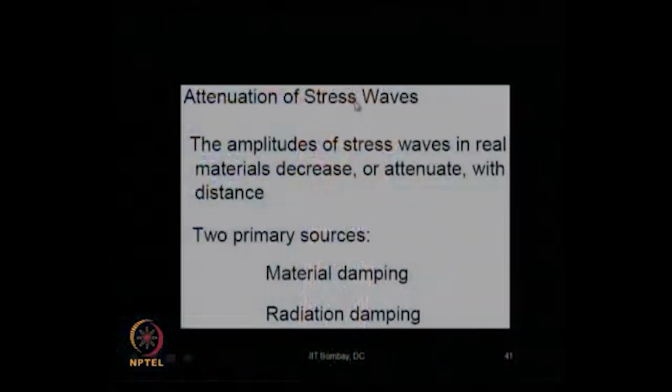That automatically reduces the original amplitude of the wave generated at the hypocenter or the focus of the earthquake. So at our site of interest, the value of the stress we should consider should be related to this attenuation. It should not be the wave amplitude generated at the hypocenter; we should not use the same amplitude in this case.